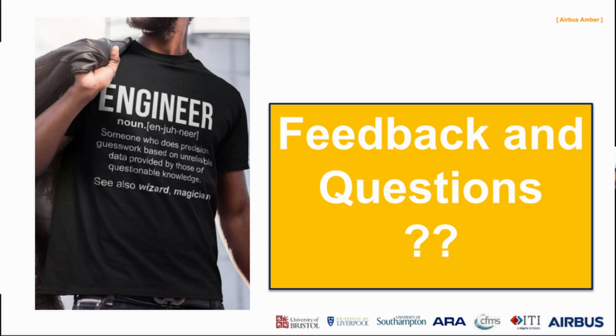And it's actually a very, very difficult question I'm battling with at the moment. How do you validate your UQ, especially in early design? I would almost say these are unvalidatable. You cannot validate your early design uncertainties without building 100 aircraft in parallel with engineers that don't talk to each other and looking at a statistical distribution of what came out, which is not going to happen. So you can invalidate, but you can't validate. Sure. In general, the truth. For model validation as well. You can invalidate your model, but you can't really say for sure that it's valid.